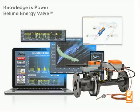And the more and more customers we talk to, they start to find their own little niche built within this valve because it is a couple of things built together. It's a combination of a control valve with a pressure-independent technology built in with it, with a flow meter, with temperature sensors also that are incorporated into this valve. And that allows us to sense what we're going to talk about today, delta T, allows us to adjust for low delta T. Very powerful things, and there's going to be a lot more of this coming up in detail as we go along.